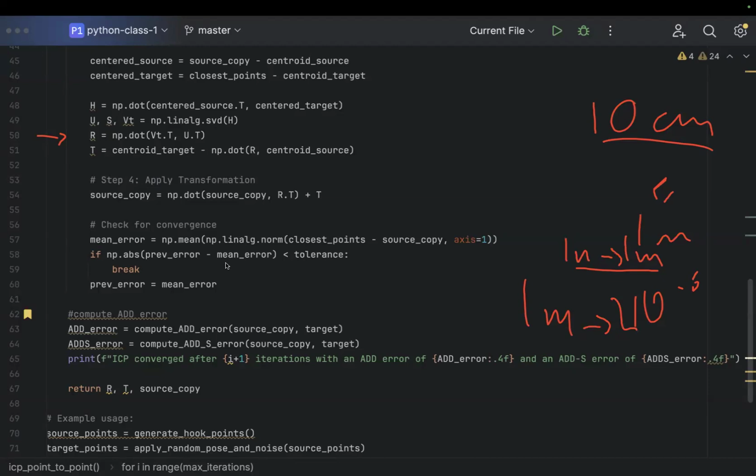So if I have some bistable system that basically increases the error, then decreases the error, then increases the error again, because my model is not alignable with the sensor data, I might actually run this forever. If my tolerance is too low, if it is of the order of magnitude of the sensor noise, it can be that I start realigning the object back and forth, because given one state, it will prefer to go to the second, and given the second state, it will prefer to go to the first. You're not guaranteed to find a minimum, not even a local minimum.